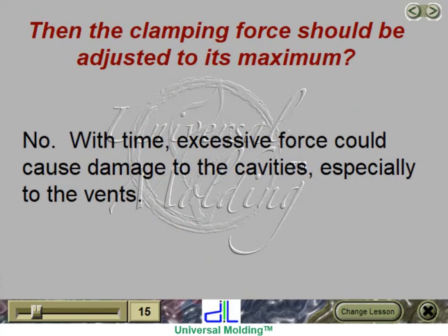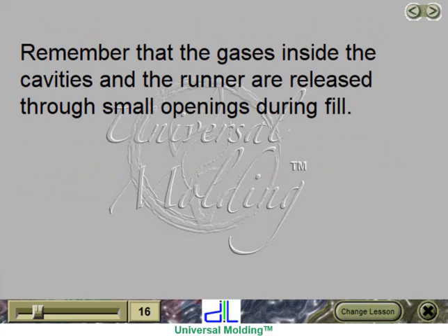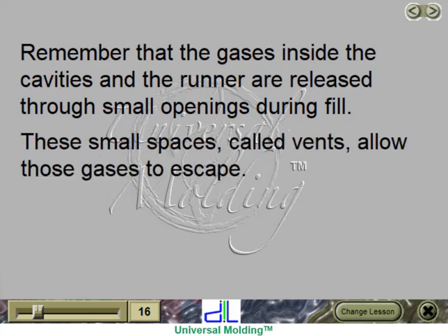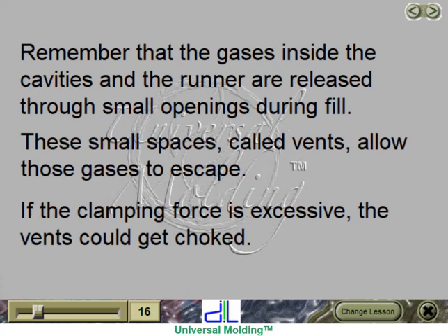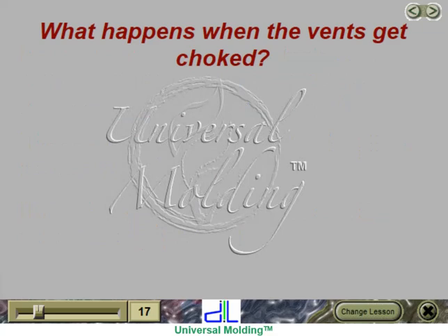No. With time, excessive force could cause damage to the cavities, especially to the vents. Remember that the gases inside the cavities and the runner are released through small openings during fill. These small spaces, called vents, allow those gases to escape. If the clamping force is excessive, the vents could get choked. What happens when the vents get choked?